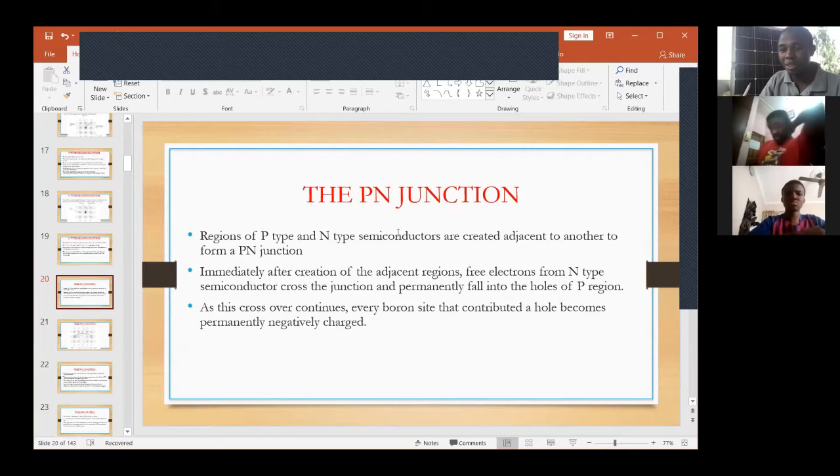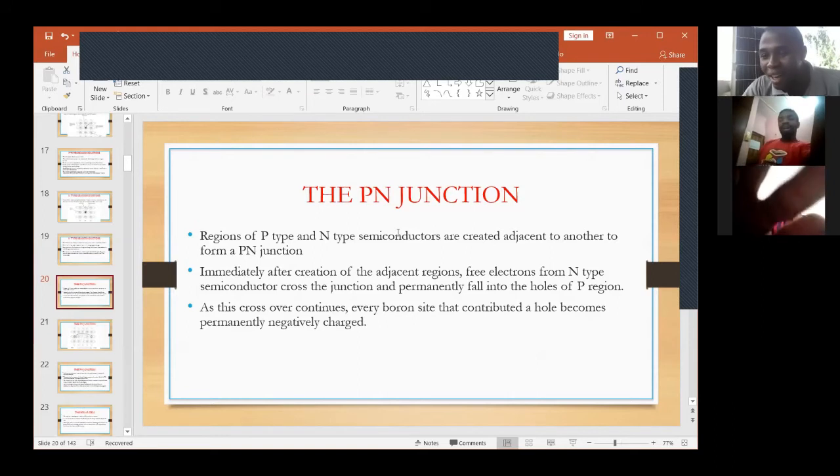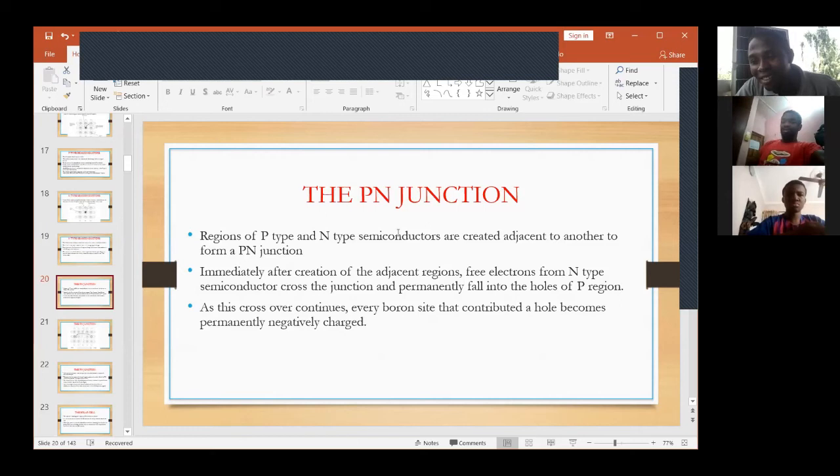So that will be the basis of our next class when we look at how to calculate. How do you tell it's 100 watts? For the volts we described 18, but for the watts, how do you know it's 100? Each cell has 2.85 watts, or 2.65 watts each cell. That's the energy generated by each cell. So if you do 36 times 2.85, you will get 100 watts. It's as simple as that.